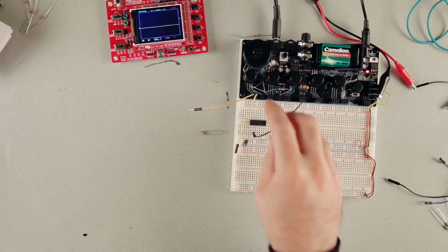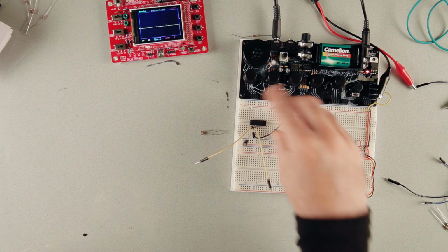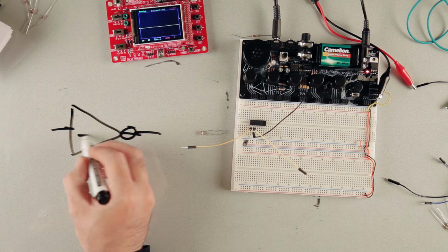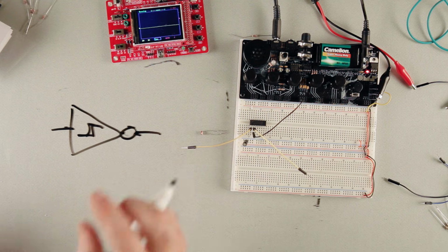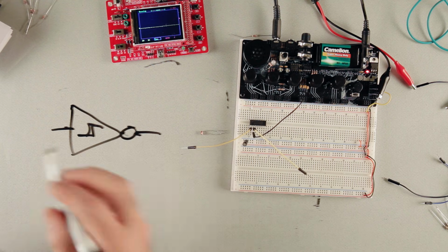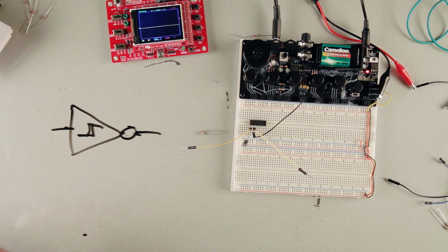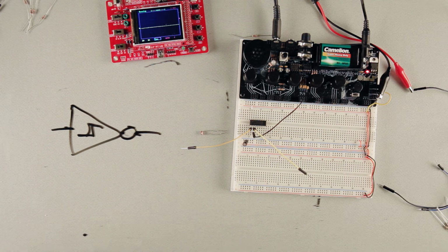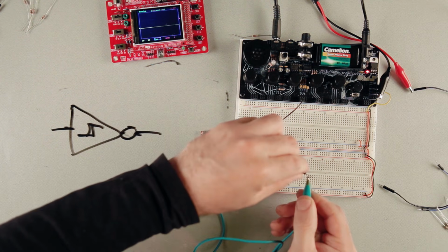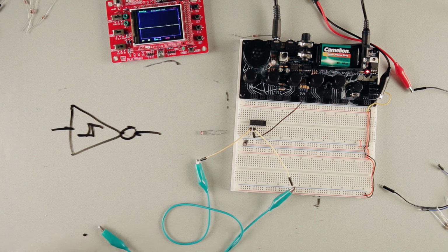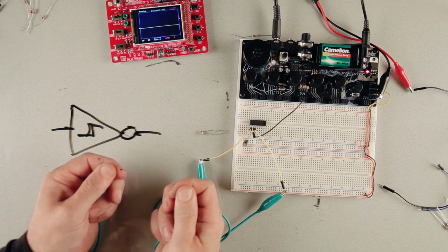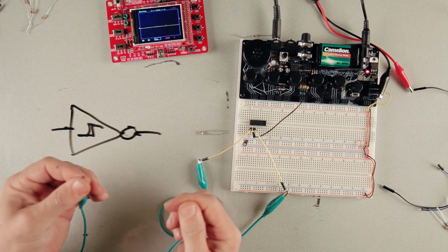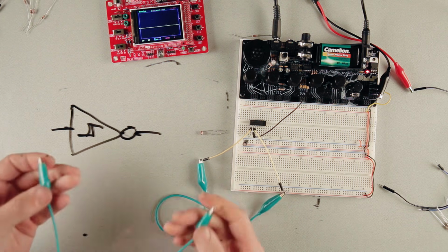So then let's try another example. So we're going to take, so this is the input and the output of our inverter. But again, I should say this Schmitt trigger, it's a special kind of inverter that I encourage you to look up and read all about. And we're going to take some alligator clips here. We're going to connect those to the input and output. And now let's see, if I touch them, you can see the pitch is going up and down. Okay, but you can see that range is not so great. It's a little too low. So how do we change the range?